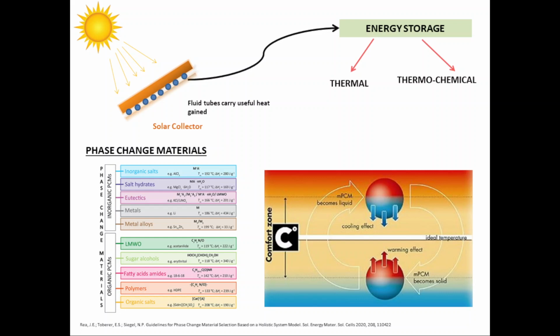So in summer, we have the collection of solar radiation greater than what we want, so that is your peak off hours, where your collection or supply is greater than the demand. Whereas in winter, your demand is more, but unfortunately your supply is less. So whatever excess energy is stored during the summer months is taken up during the winter months. To maintain these energy fluctuations during the year and meet the seasonal demands, we go for a thermal energy storage system.